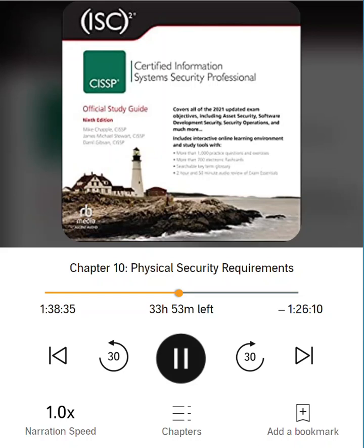Benefits of gas-based fire suppression include causing the least damage to computer systems, extinguishing the fire quickly by removing oxygen, and being more effective and faster than a water-based system. CO2 is an effective fire suppressant, but it poses a risk to people. If CO2 leaks into an enclosed space, it can cause asphyxiation at only a 7.5% concentration. Fire suppressant use of CO2 is often at 34% or higher concentration.